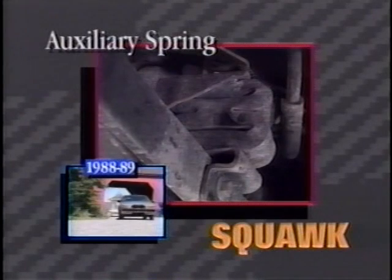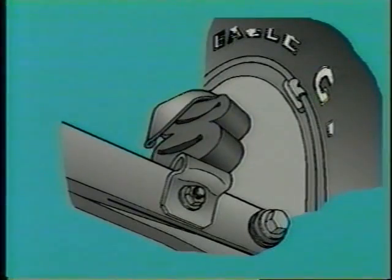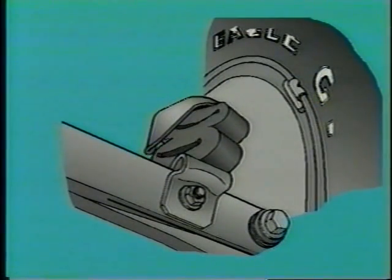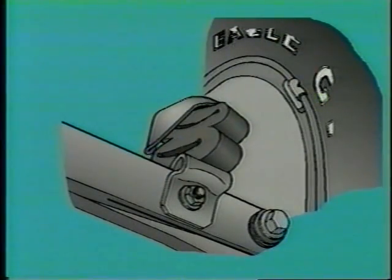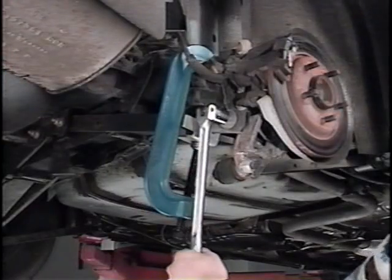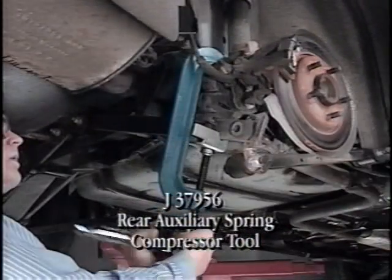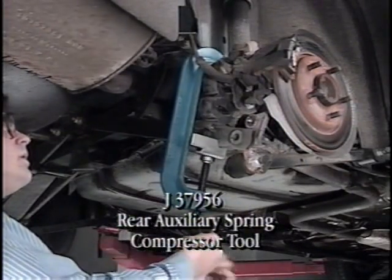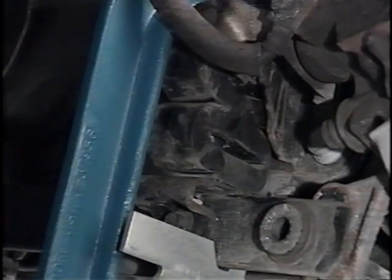During normal suspension movement on some 1988 and 89 cars, contact between the rubber auxiliary spring and the rear of the upper mount bracket can result in a squawk or squeaking noise, particularly when the spring assembly is wet. To eliminate this squawk, use the special auxiliary spring compressor tool to remove the spring assembly and reposition the spring so that it does not contact the rear of the bracket. Then use the spring compressor tool to reinstall the spring assembly.